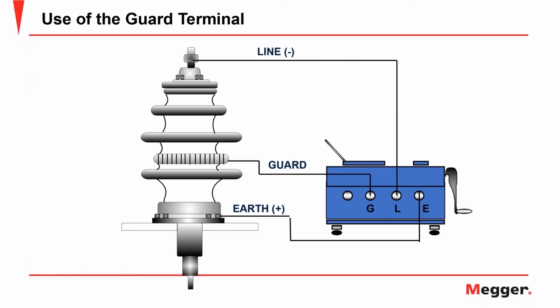This would be on transformer bushings. What they found was that these, of course, are typically outdoors, and there's moisture and dirt traveling over the surface of the bushing from the minus to the positive terminal. Tests would be performed, let's say, in the morning when there was morning dew on the bushing, and the readings would be comparatively low.